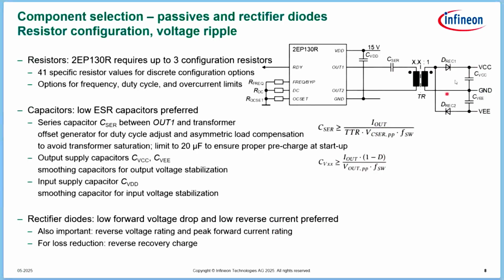This is basically the junction capacitance of these kind of diodes, where we want to make sure that if they need to switch on and switch off, basically, that this capacitor recharge is not limiting our energy we can transfer, and therefore reducing then the losses in overall the system.